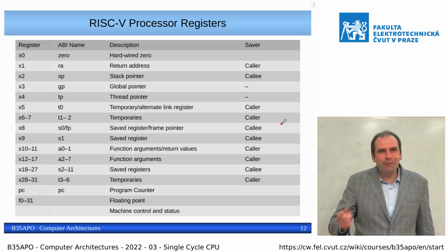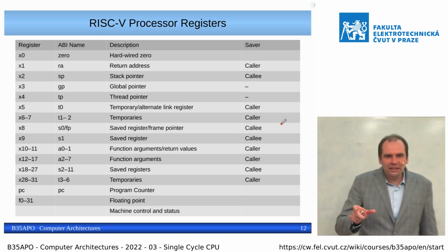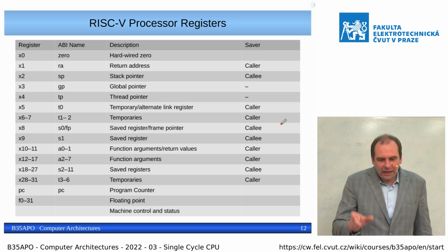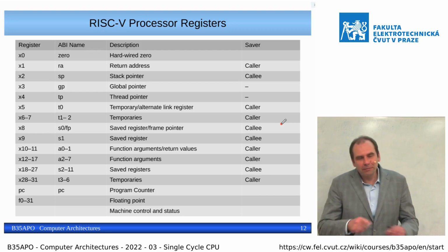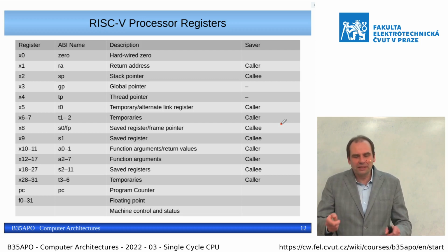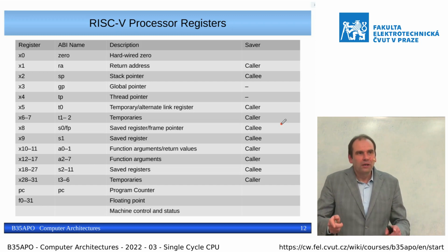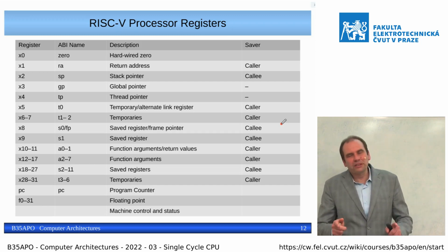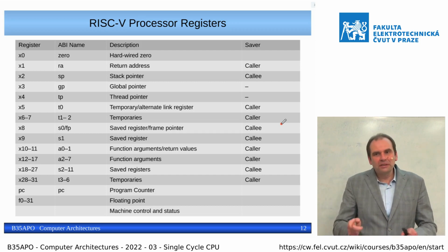Usually some processors raise an exception if you try to access data which are not naturally aligned. So it means that, for example, 32-bit data for a byte-addressable CPU has to start at an address divisible by 4. But most of today's processors are able to cope with it, even for instructions.